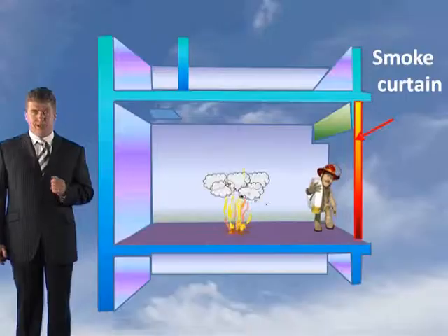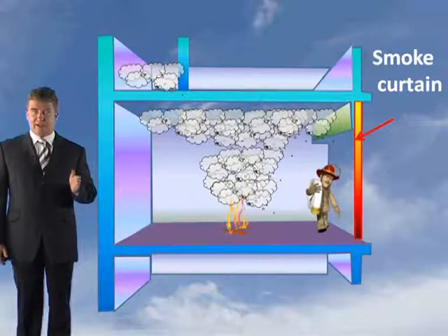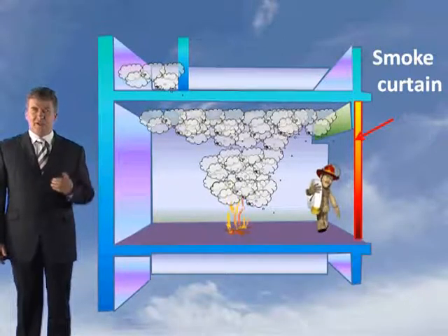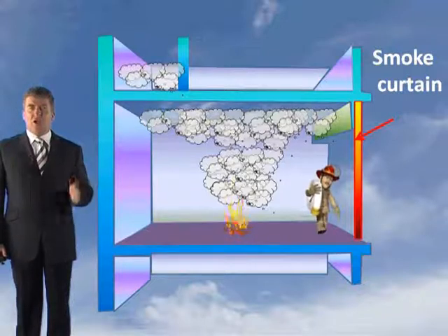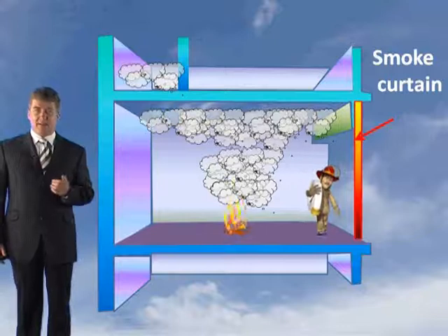Now, free-hanging smoke curtains can be divided into two categories. You've got those which fall to floor level and completely seal areas from a smoke compartment. I mean, these might be installed along balconies, for example, to form a closed atrium. So it actually closes off the atrium. In effect, it has the same effect as a compartment wall.